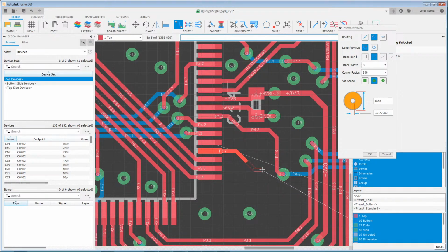As you go around in the trace, you'll notice that it switches from this one, which was one complement, one path, and then as we go around and we break over here, it'll automatically adjust to the different complements as needed. If you ever find that it's not giving you the one you want, you just right click and you get the other one. But most of the time its automatic adjustment will work.